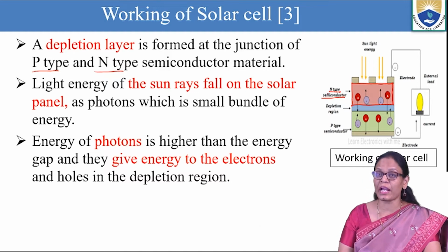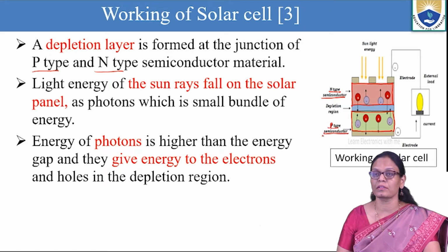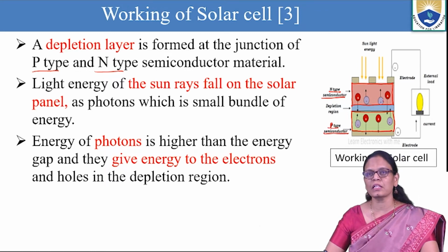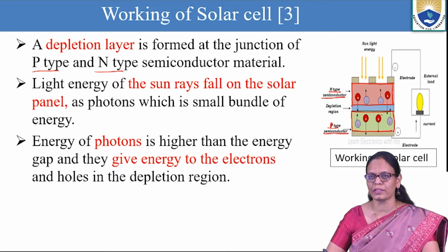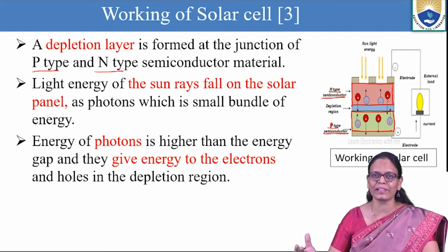So we have the N-type layer and then this green part is the P-type. So this is the P-type semiconductor. Now when we bring this P-type and N-type together, in a normal p-n junction, what happens? There will be movement of electrons from the N side onto the P side and movement of holes from the P side to the N side. This we call diffusion.